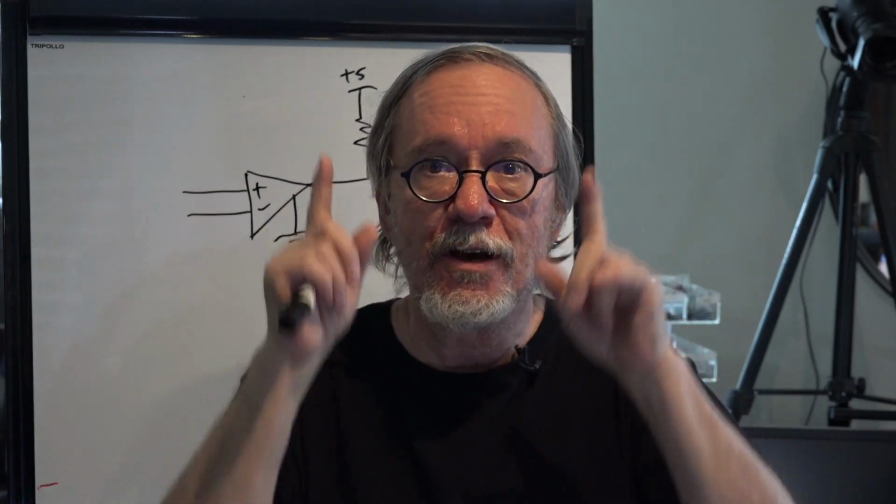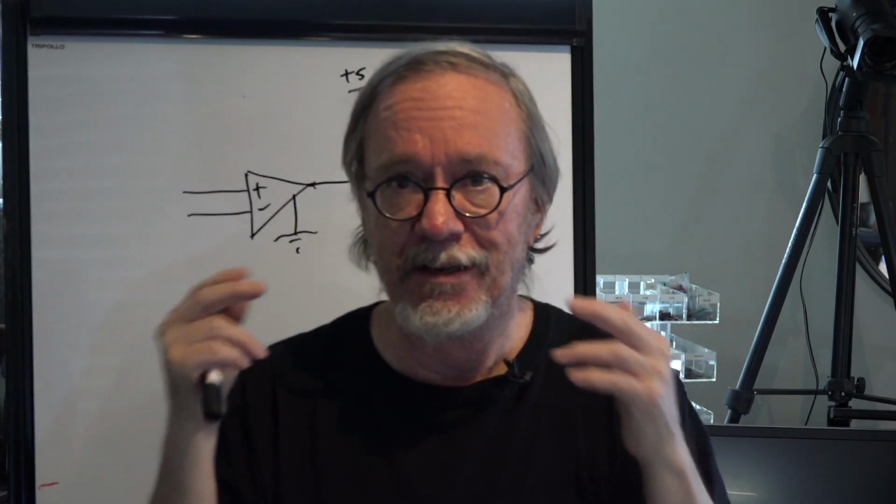Well, they call it the impedance. For now, let's say it's the same as the resistance. That probe comes in, it's very high. Very, very high resistance. The higher, the better. It's 10 megohms, 10 million ohms. Now you would think, that's a lot of resistance. Well, yeah, it is. But in this case, it means I'm not even there. In fact, the higher the resistance goes, pretty soon you get to the air, where nothing's happening.